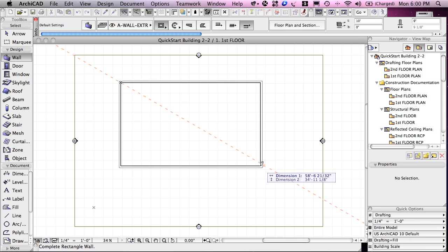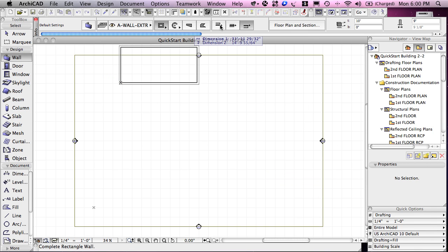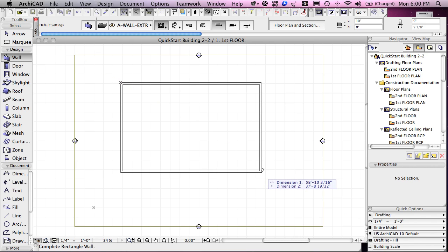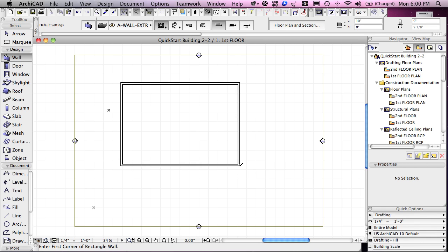So pay attention when you're drawing which side is actually connected to the pencil, which side has the heavy reference line, because the dimensions that you put in will refer to the lengths on that particular side or that reference line. So I'm going to again put it back to the direction that gives me the box of walls where the outside is what I'm specifying, and I'll type in my 50 tab 35, which would be roughly equivalent to 15 and 10 or 11 meters. So now I've got a box of walls.